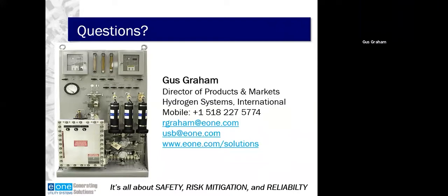The second question was in regard to temperature compensation for accuracy. Yes. So E1's approach to that is that we have a cell block heater that's part of the thermal conductivity cell. What we do is we elevate the temperature of the gas above the ambient temperature, and that enables us to eliminate the ambient temperature effect on the gas sample, to ensure an accurate response across all ambient temperatures.